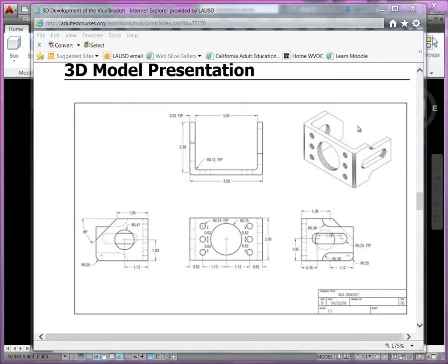If we didn't have any of those cutouts, the basic shape, the basic form of our bracket is U-shaped, of uniform thickness, okay? Now considering the standard views that we're showing here, such as the top, front, and right side, what you need to be able to do is to picture your subject or your solid that you're trying to model within a cube and try to determine which view of the cube reveals the basic profile of the model that you're trying to create.